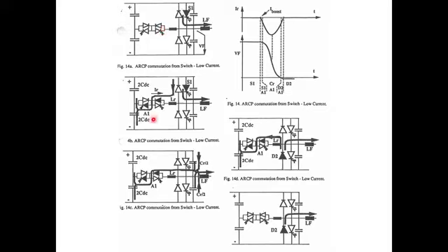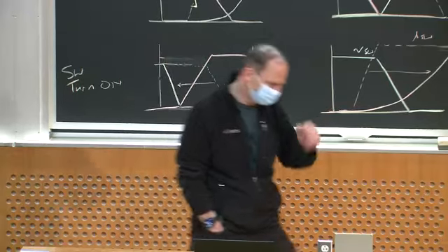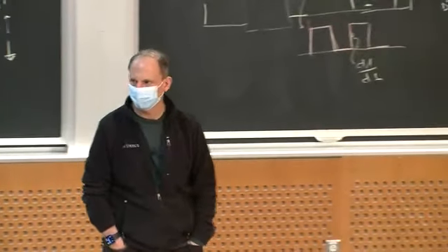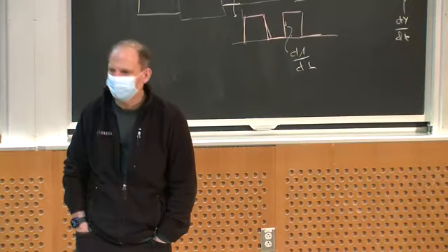And because of the snubber capacitors, you get reduced dV/dt on the switching transition, and hence reduced EMI driving your motor. So that is sort of a lightning introduction to soft switching and some of its benefits, and just an introduction to some of the ways you might go about it.